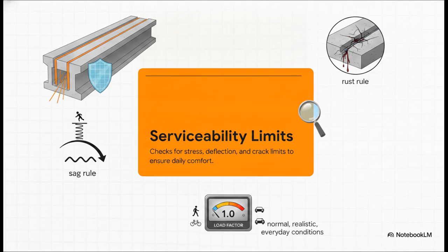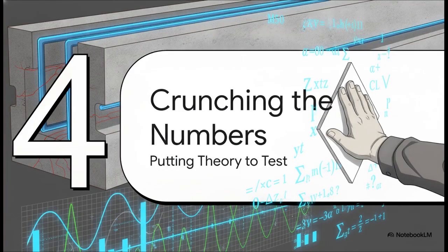Notice that for these checks, we use a standard load factor of exactly 1.0. We aren't magnifying the loads here because we are evaluating normal, realistic, everyday conditions. Part 4, crunching the numbers and putting all this theory to the test.